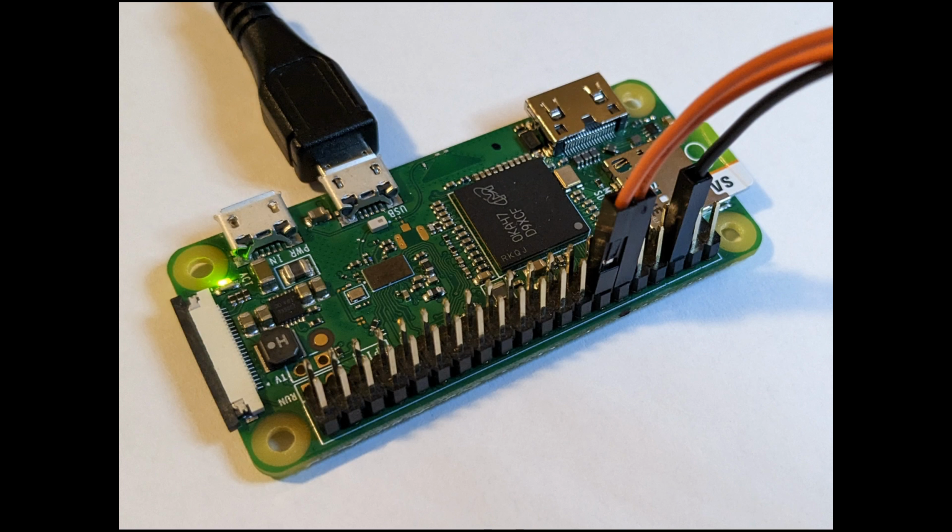Let's use Scopey to measure the rise time of the Raspberry Pi. I have signal 1 plus connected to pin 18 of the Raspberry Pi, and then 1 minus and a ground from the M2K are connected to ground pins on the Raspberry Pi. The Raspberry Pi has some useful features for this test. I have software that sets up a hardware generation of a square wave at 2 megahertz, and the software can also control the drive strength of the outputs, which can range from 2 milliamps to 16. So we can see if changing the drive strength changes the rise time, which theory dictates it will. The higher drive strength can produce a faster rise time.